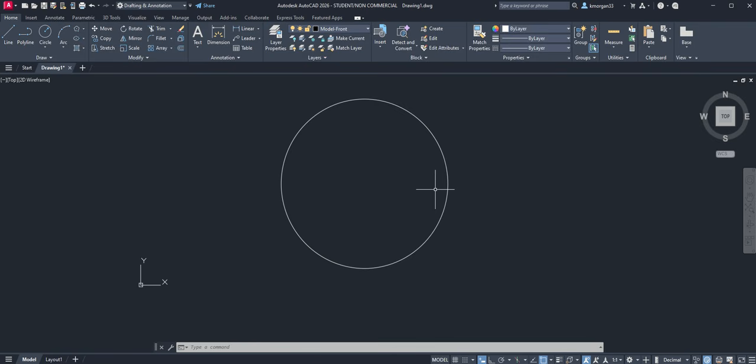The next one is, of course, you can practice the two-point circle with those 2 points. You can do that. So you can go circle, and it will give you the circle here. I type it straight in and show you how to do it. Of course, if you don't want to call it by the command, you can also repeat it by pressing Enter on your keyboard, and it will give you the last command. It's going to pop right back up. I will show you later.